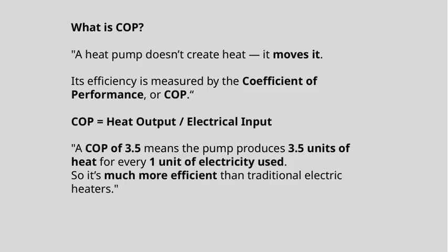So, a higher COP means you're getting more heat for less electricity, which is better for both your energy bills and the environment. Connecting this to our overall theme, understanding COP helps us see why heat pumps are such an effective and sustainable choice for heating solutions today.